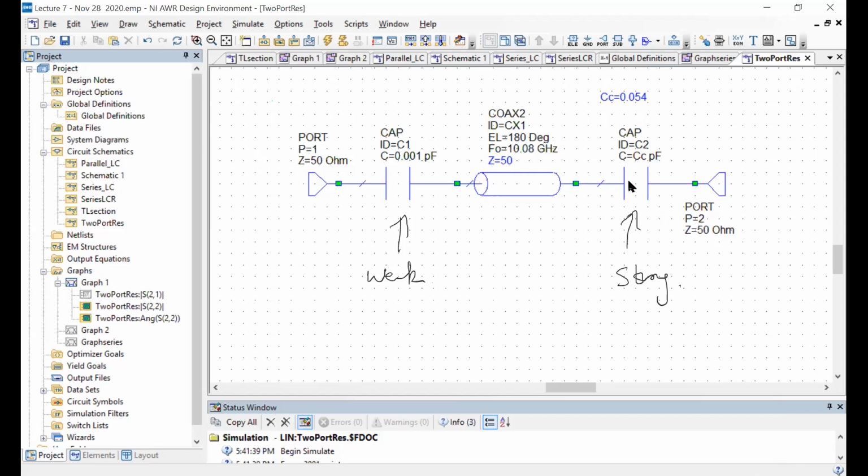So you still have the same kind of standing wave pattern, except now that this is a very weakly transmitting mirror. So it still supports, and in this case it's a capacitor, so it still has basically an open-end kind of boundary condition. And correspondingly, the loading of the resonator because of this capacitor is going to be much smaller, and only the loading will be there due to this strongly coupled port system. Okay, it's very important to choose the ratio of the capacitors to be sufficiently different that the loss of the resonator is dominated by this.